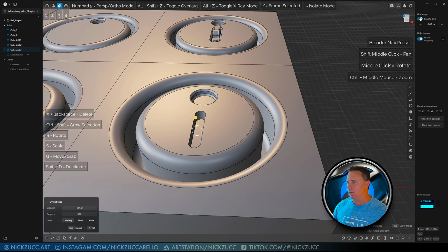If I want to make sure that I've matched this face up here, just to be extra careful about it, I can tap 3, select the face, and then I can go back here to this match face and then just click one of these faces, and I'm good to go on that. Okay. All right. So to make these corners, I'm going to tap 2 to select my edges. I'm going to select all these right here. I'm not going to select the bottom one, so you can see how I'm working my way around here like that. And then we're going to use this tool here.